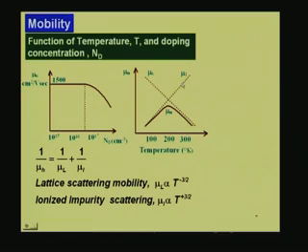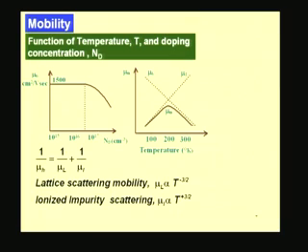That is because if the temperature is higher, the electrons have energy to move faster and they do not get bothered by the scattering of these ionized impurities. Higher the temperature, less is the scattering, so we get higher mobility. That is what is shown here. That is one mechanism of scattering. There is another scattering mechanism which I put by this line, that is mu L, that is called lattice scattering mobility.